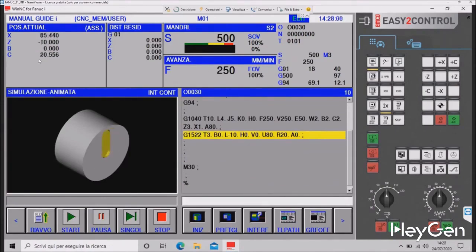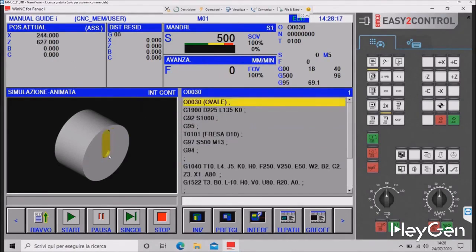And you see that we're making 2 passes of 5 millimeters. Let's restart. Look, I go in, I widen out to -5, which is the pass I set as the depth of the pass, and then to -10. This value must correspond to this value. Do you remember the 2 masks?